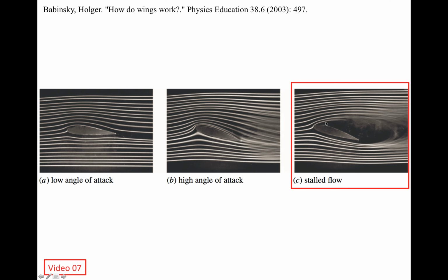So by pitching the blades to increase the angle of attack, we can deliberately induce the stall condition on certain portions of the blades. By inducing stall, we can limit the total amount of lift forces and also the torque acting on the blades. This pitching strategy for regulating aerodynamic torque is called active stall.